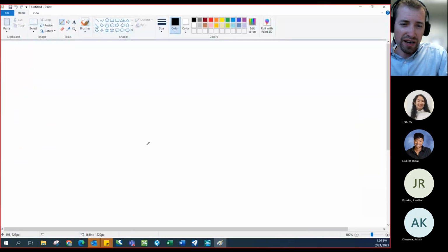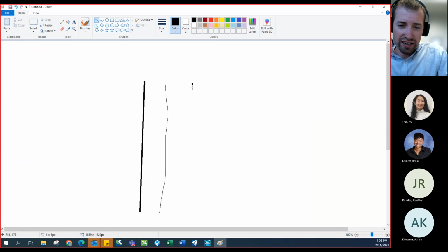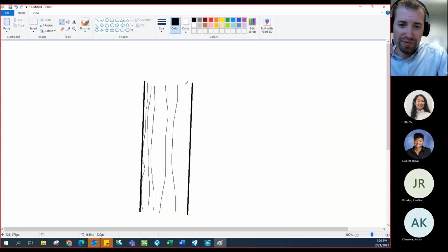We have an imaginary channel, a perfectly straight channel. The contours of a perfectly straight channel are going to be like this, down the bank. So always start there when thinking about how to lay your cross sections. They're perpendicular to the direction of flow.